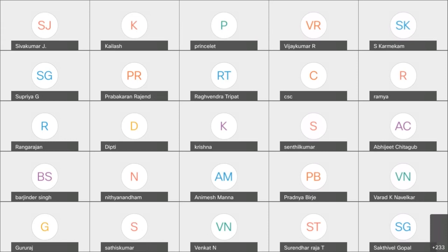I can make it a specific question in this case. The supplier hasn't given the actual failure in time. Whatever base FIT is given is as per SN norms. That is 80 FIT. So for that component, do I have to consider it according to my application, considering the temperature profile and the working profile of my application? The 80 FIT, yes, based on your profile you need to reconsider.